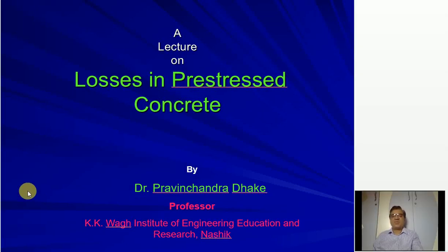Hello students, today we will discuss the next topic, that is losses in prestressed concrete. Now all of you understood what exactly prestressed concrete is. So let me once again define prestressed concrete. It is the concrete in which there have been introduced stresses of such a magnitude and distribution that the stresses resulting from external loading can be counterbalanced to a desired degree.